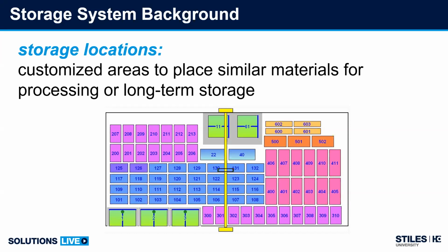So I have 2 suggestions. If you're going to design your own colors for the groups, try to stay away from the dark colors. You can't change the shade of the numbering. So with the dark shades, the numbers become very hard to read. There's a blue line that shows up on the edge of the board to show you the level of capacity. How much room do you have? Those become very difficult to see. And try to stay away from the bright green colors because that gets confusing. Is it a storage location or is it a machine? Is it a conveyor? So other than that, you can do whatever you need to with the colors.